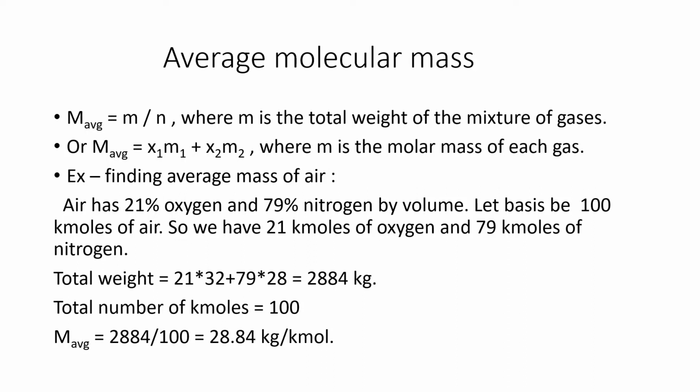As said before, by Amagat's law, volume percentage equals mole percentage. So if you take 100 moles or 100 kilomoles of air, we have 21 moles of oxygen and 79 moles of nitrogen. The total weight will be 21 into 32 plus 79 into 28, because 32 and 28 are the respective molar masses of oxygen and nitrogen.